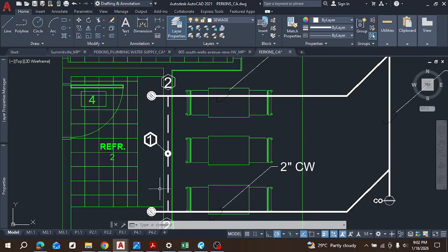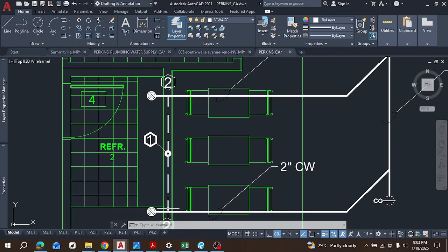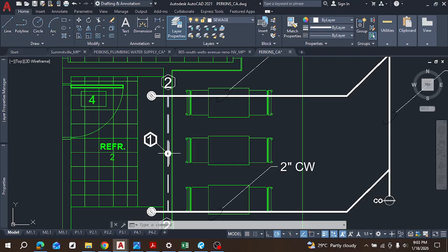This is going to be a circuit vent, because I remember saying that we must always vent floor drains, even though they don't have heavy flows, because one day they might. You never know. It's usually good to design for the worst day possible. So this line indicates the vent line. This goes vertically up into the wall, and then within that wall, it meets up here and then it goes up.